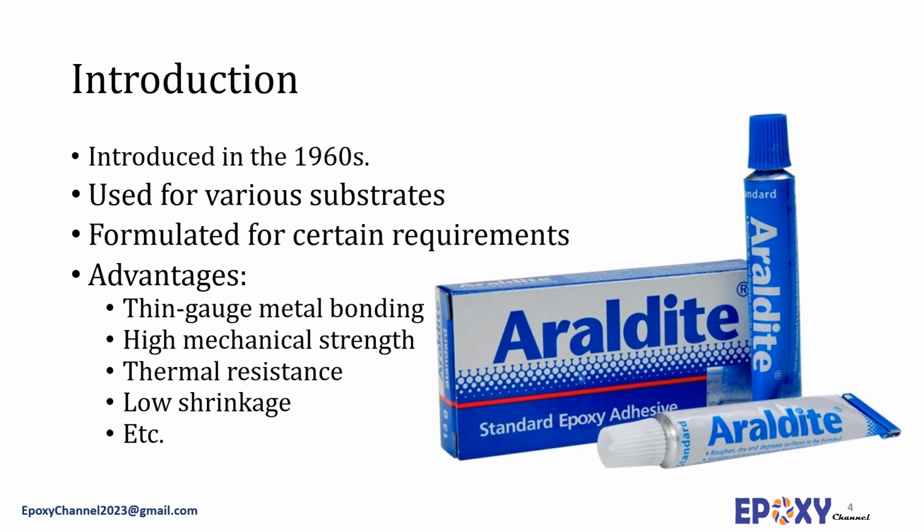in the joint. They can be formulated for certain requirements, and the use of these adhesives can also facilitate the fabrication of complex shapes. One of their advantages is that they are capable of being used for joining thin gauge metal substrates, for example, in honeycomb assemblies. Their other advantages include their high mechanical strength in terms of tensile and compressive, their thermal resistance, and substantial toughness. They also result in low shrinkage and have a high adhesive strength.